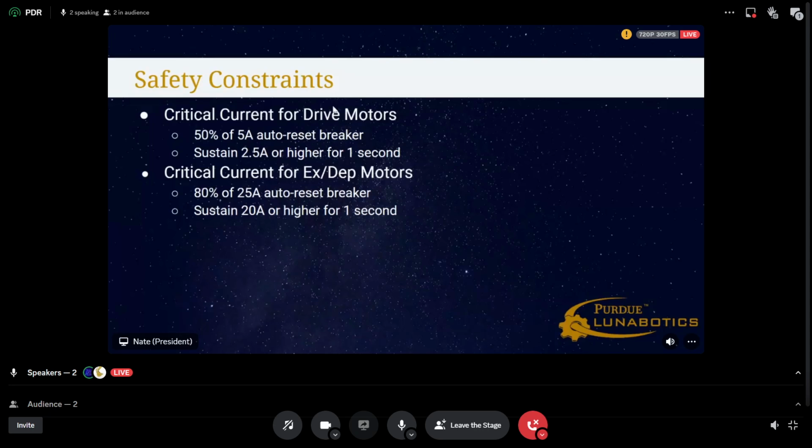Okay. That 0.2 meters per second is very fast. With 8 centimeters per second, we're looking at about 2 minutes to get from starting to the excavation zone, and then traveling from the excavation zone to the deposition zone, about 40 seconds, which I think are all reasonable numbers. But that isn't including the time to adjust orientation and all that stuff. That's just an average speed. Right. Okay. So that adds time.